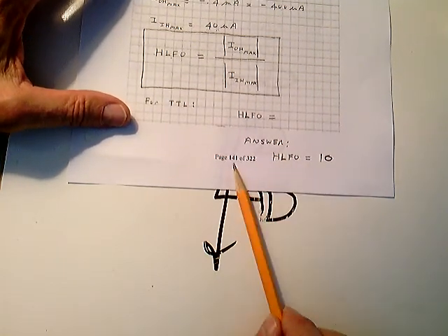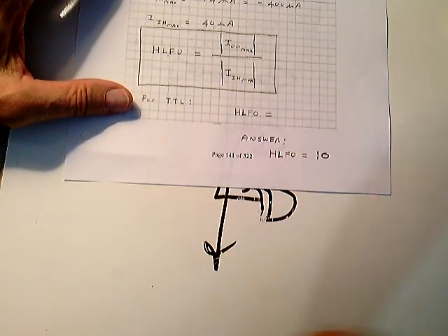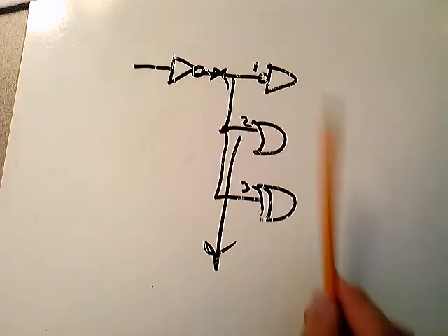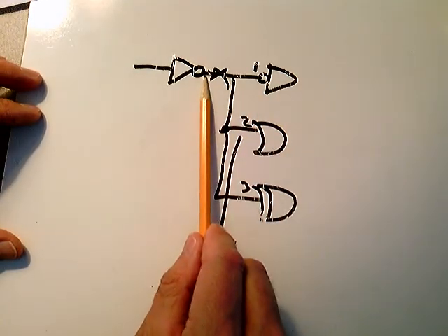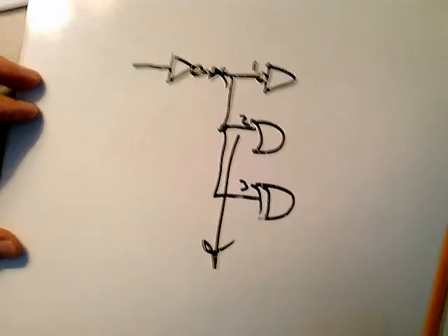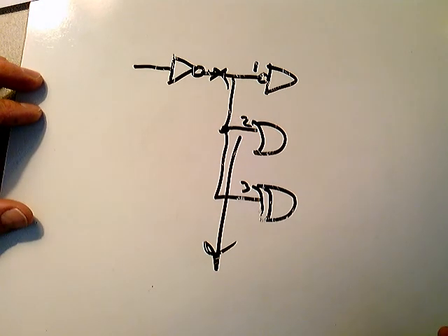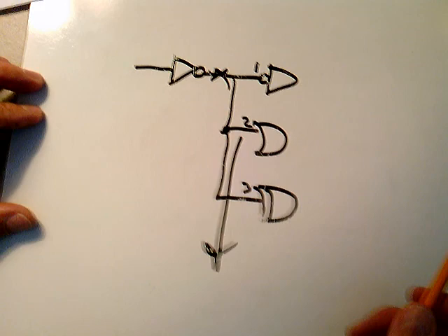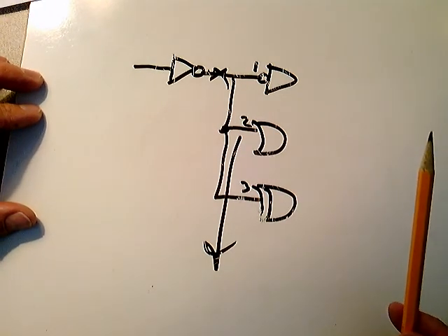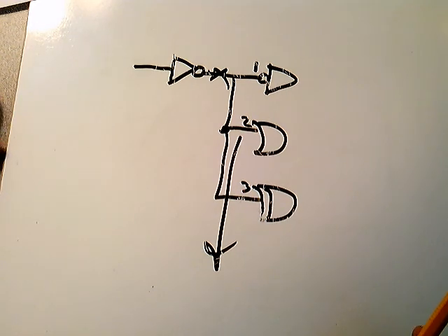Now, the low level fan out and the high level fan out were both 10. You could drive 10 different circuits here. You could go out to 10, take one output, TTL, and you can go to 10 different circuits. They're guaranteeing that. But the low-level fan-out and the high-level fan-out aren't always equal. Sometimes one's 10 and the other one's 20. Sometimes they're the same, like in TTL. So you'll work homework problems, and hopefully that'll clear things up for you. That concludes this lecture.